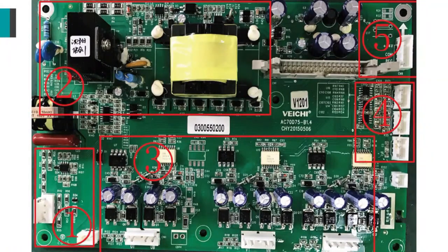Very integrated panels. And then with these test methods and the test meters, especially the multimeter and current clamp I just introduced, when you go to site, please take the multimeter and current clamp and you could judge which part is damaged almost in 70%. If you could still not find the problem, please contact the distributor or contact our engineer directly. We could help you do the fault debugging and check the problem.